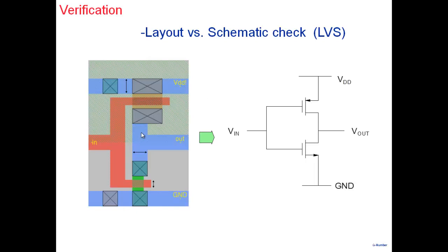All right. The other thing that happens is, once you extract the schematic here, along with that, now you have the exact lengths of wires and everything. You know that this PMOS is connected with the wire to the NMOS, and the wire length is so much. So you have all the parasitics available to you. So when you extract the schematic, along with that, you get all the parasitics, all the wire lengths, everything becomes available here. Now, if you do a simulation, the simulation will give you accurate values of delay.